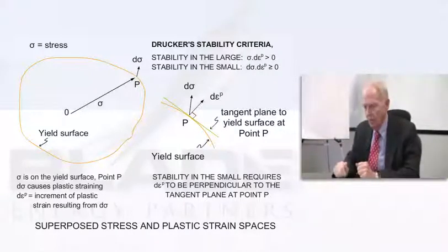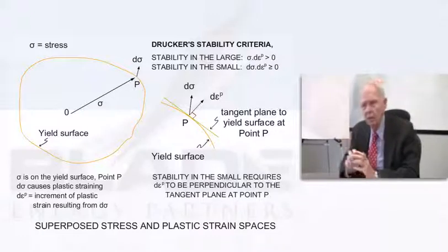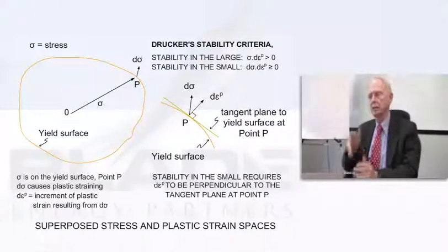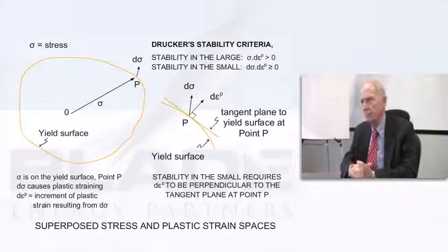The other is to start with a crooked column. And in fact, the crookedness, that is the out of straightness of the column, appears in some design codes for structures. So people even know kind of what the limits would be.